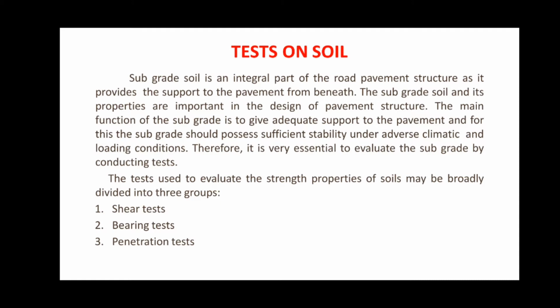The main function of this subgrade is to give adequate support to the pavement, and for the same reason the subgrade soil should have the capability to support the pavement with utmost stability under adverse climatic and wind loading conditions. Hence, it is very essential to evaluate the subgrade by conducting tests either in the laboratory or in situ tests or field tests.